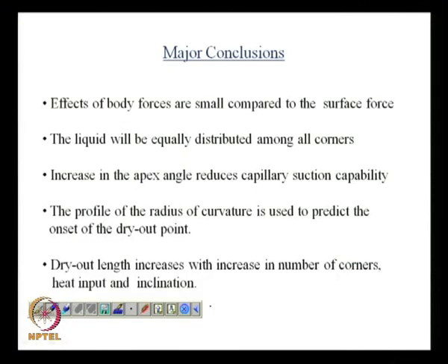And obviously dry out length increases as you increase the heat, as you increase the inclination, and as you increase the number of corners. So, that is all I wanted to discuss today about micro heat pipes, and in the next class I will talk about the associated but more important problem, which is how to calculate the pressure drop in such situations. Thank you.